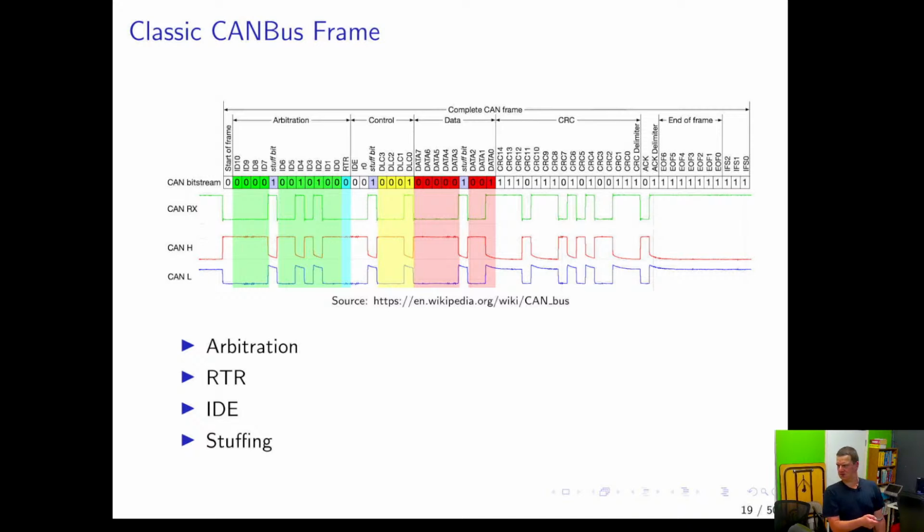Does that make sense? No. So that is for the message that just received it, like before the frame. No, so the ACK field is for the sender to know that another node on the network received the message. This specific frame. So the reader would be reading, and when it gets to here, they'll erase that bit.